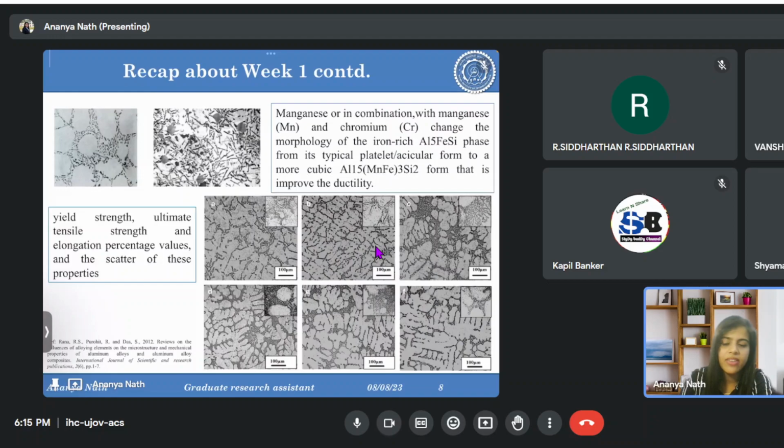Aluminium barely has phases like austenitic. Like we have austenitic steel, martensitic steel, so martensite, pearlite, austenite we have in steels. Those types of phases are not there in aluminium, which is a great advantage for the researchers, because we don't have to worry about the phases much.